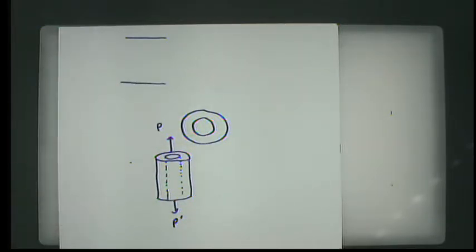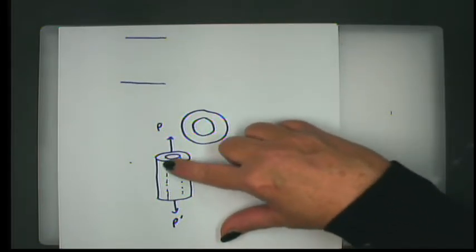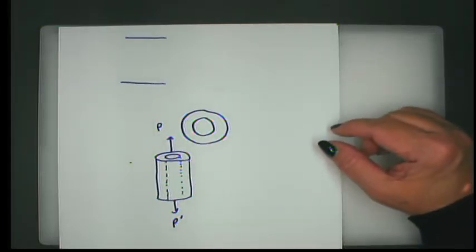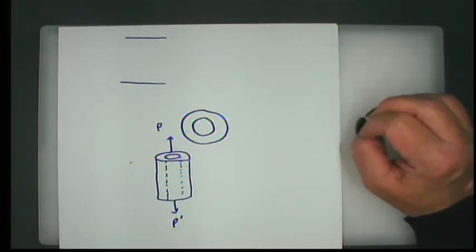In the last problem, when we had two members that were in series, more or less, with each other, we could add together the deflection. But if the integrity of the weld or whatever holds these two materials together remains, what can you say about the deflection of the aluminum jacket compared to the deflection of the steel core?